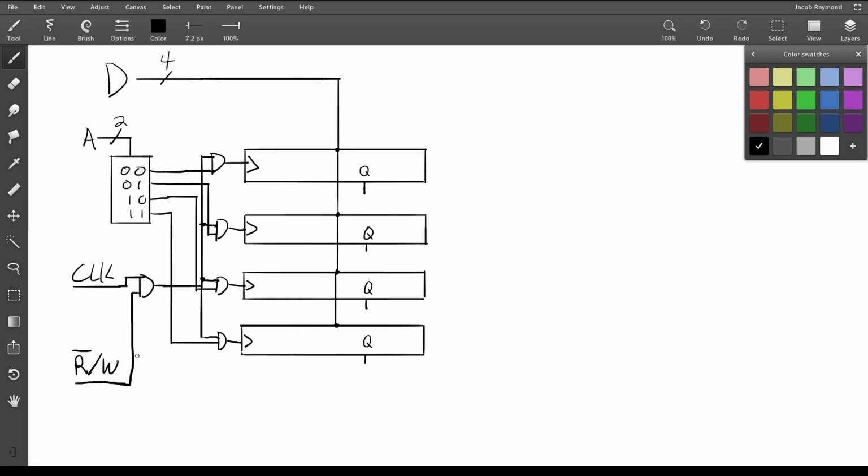So, to read, we need to choose between some of these options here. And whenever you hear that sort of, I need to make a choice or I need to choose some sort of output, the de facto thing that you should think about when dealing with circuitry is a multiplexer. That's exactly what they're meant to do. They're meant to take in a bunch of inputs and another input to select which one of those that you want, and then output that.